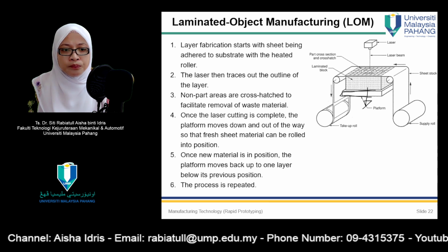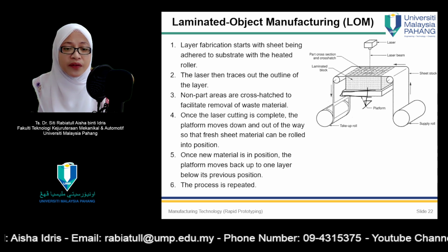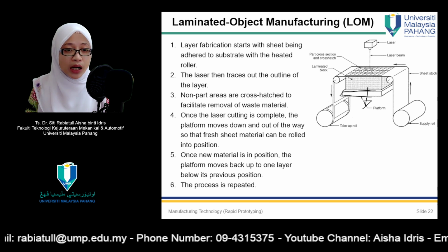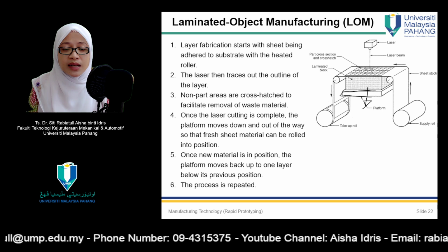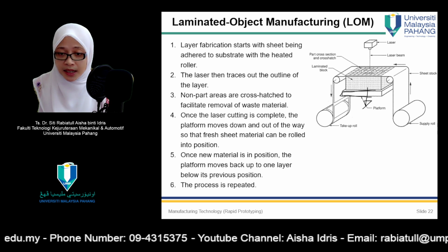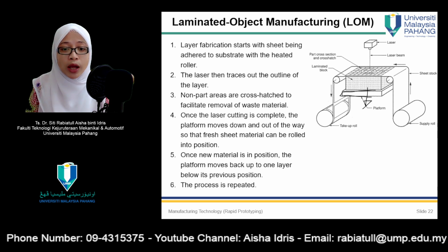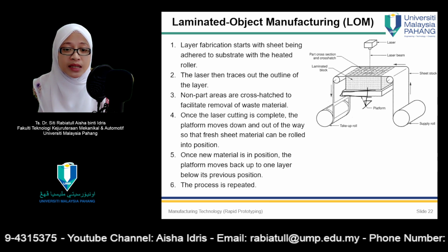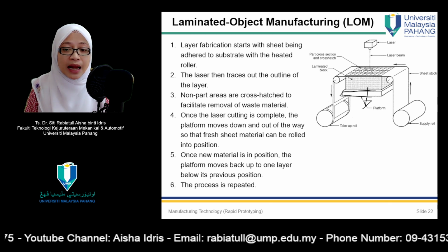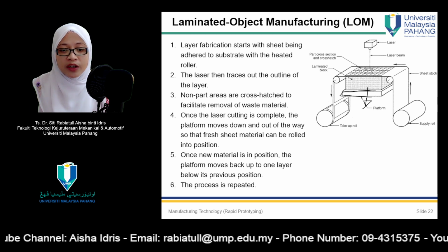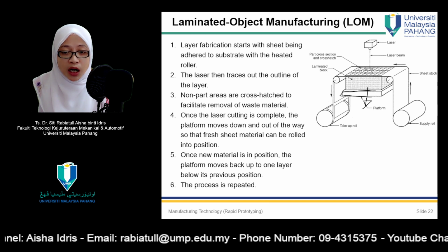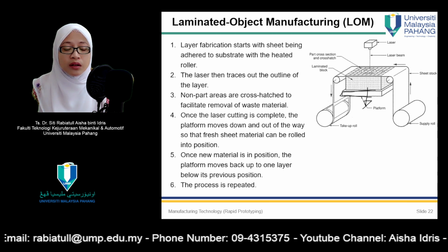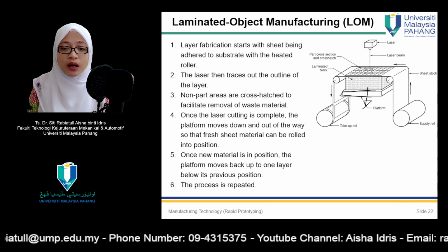The preparation phase in LOM consists of slicing the geometry model using the STL file for the given part. The slicing function is accomplished by LOM Slice, the special software used in LOM. Slicing the STL model in LOM is performed after each layer has been physically completed and the vertical height of the part has been measured. This provides a feedback correction to account for the actual thickness of the sheet stock being used, a feature unavailable on most other RP systems.